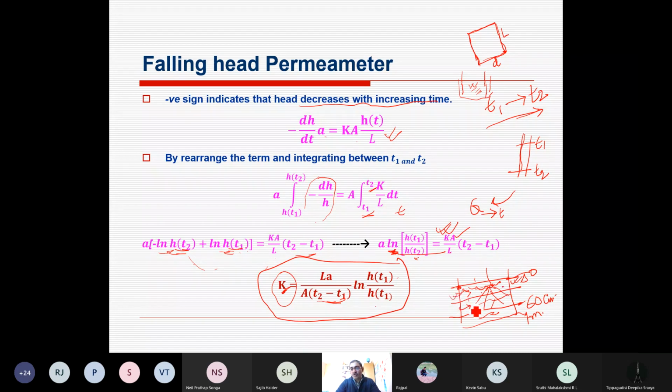But the soil below this is always compact because it is not disturbed after any time. So manipulation generally is done up to say 15 centimeter usual, but not more than 30 centimeter depth for agricultural purpose. So the soils are compacted at the top and further compacted below that top soil. That makes a kind of different characteristic layers of the soil.